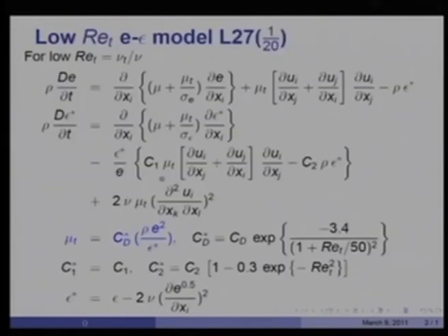So, let us consider the low turbulence Reynolds number forms of the kinetic energy equation and the dissipation equation. We are going right up to the wall. The definition of epsilon is changed to epsilon star now, where epsilon star is defined here. Epsilon star is equal to the isotropic epsilon minus 2 nu (d k^(1/2)/dx_i) squared, and I'll explain why this change is necessary.